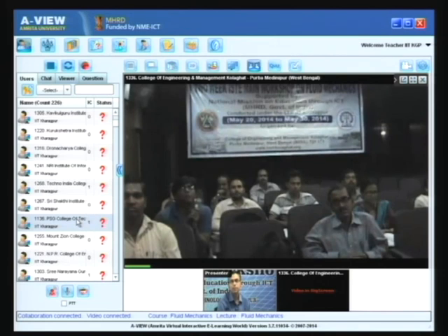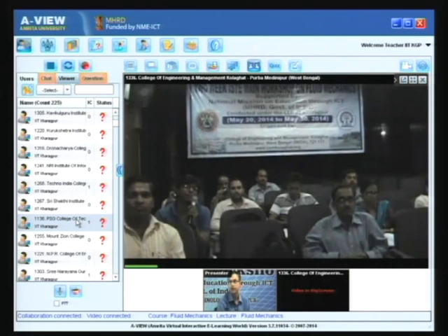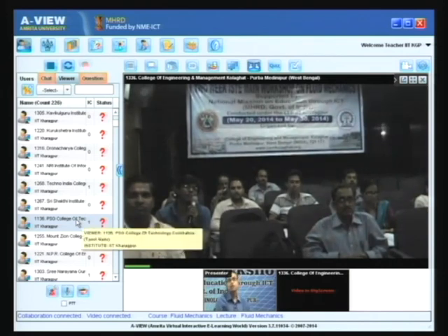All the 6 faces will have normals along x1, x2 or x3. With the element I took for the derivation, one face is arbitrarily oriented in terms of its normal, and 3 other faces have normals along x1, x2 and x3, and it makes a closed volume. But if you take a cube, it is a closed volume with 6 faces, but none of these faces is arbitrarily oriented; all of them have x1, x2, x3 as normals.